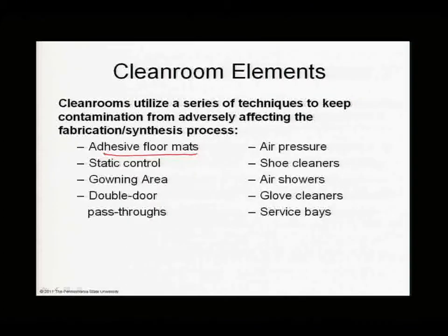Remember, the shoes have shoe covers on, but it's still possible to pick up something. So adhesive floor mats are commonly used. You have to worry about electrostatic discharge. We talked about that. You have to have a gowning area. You have to have proper door design and pass-throughs. Let's just talk about that for a minute.